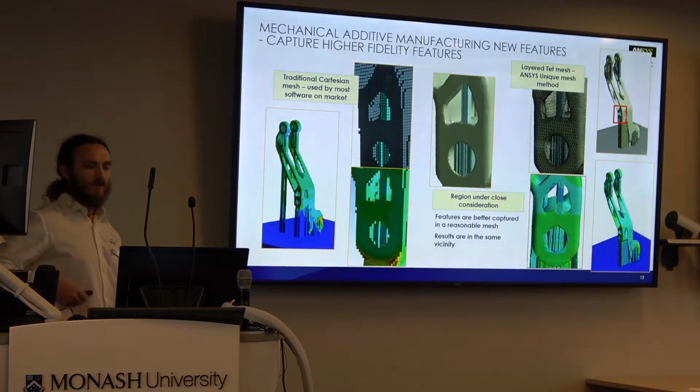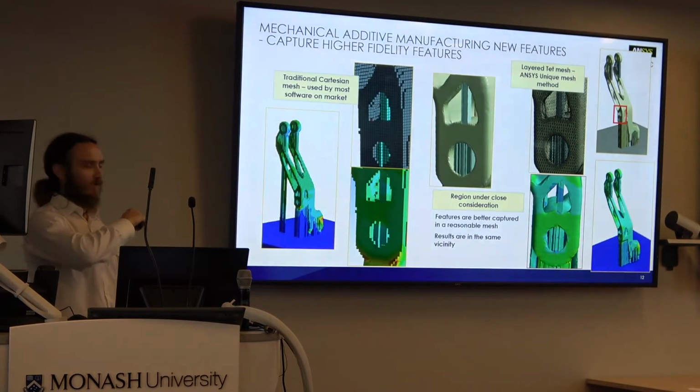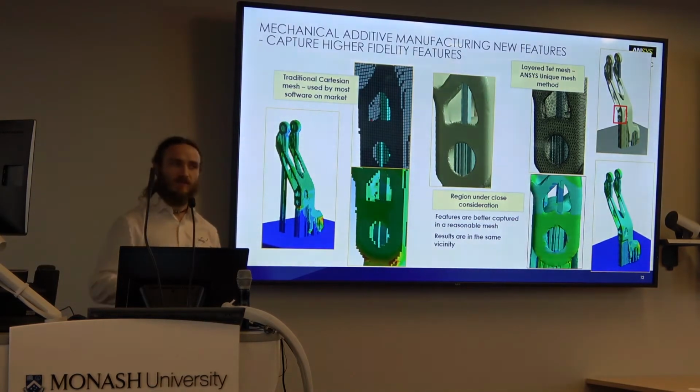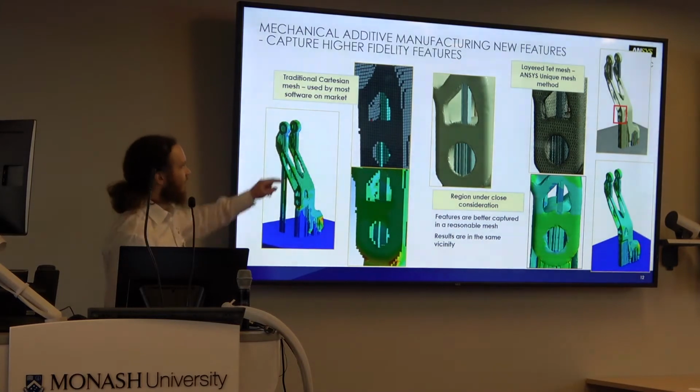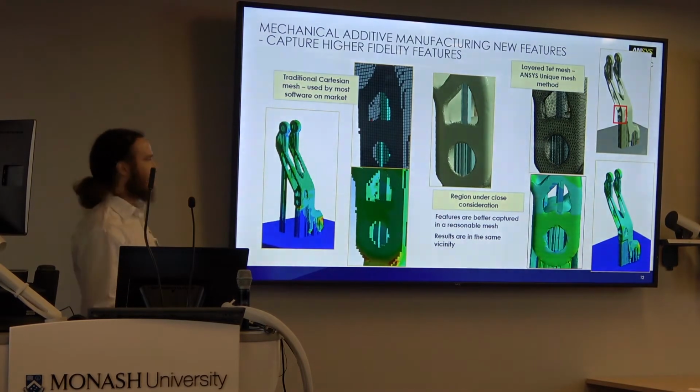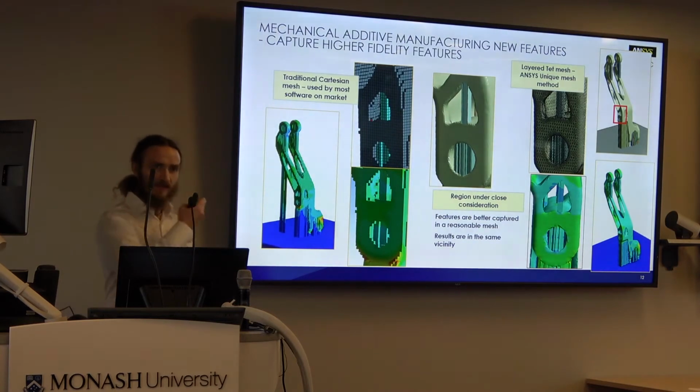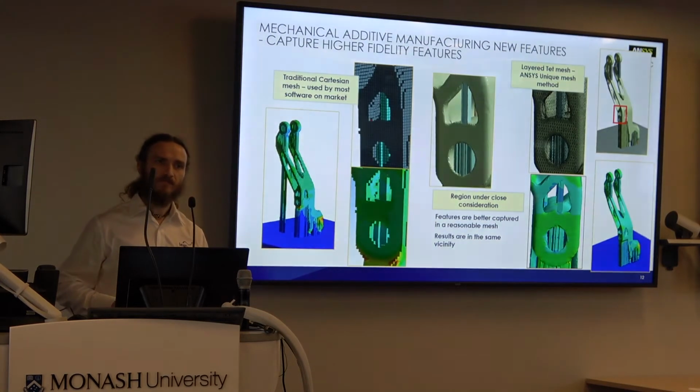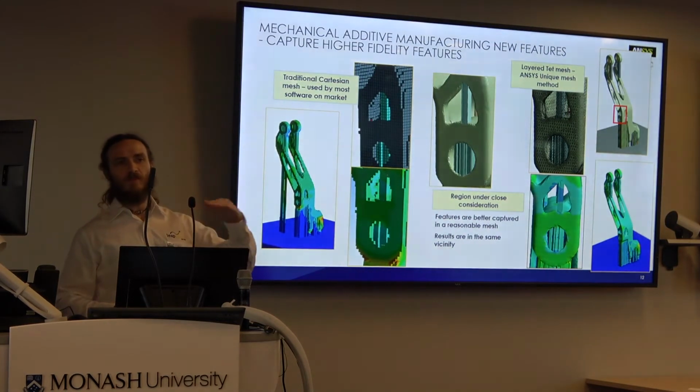Because it's a layer by layer process, we need a mesh that allows us to simulate that. So a Cartesian mesh, like this one that you see here, is a perfect candidate for 3D printing. But each layer is about 50 microns, but if you are assuming the mesh is in millimeters, you are approximating. Each layer of mesh represents about 10 layers. Yeah, yeah.